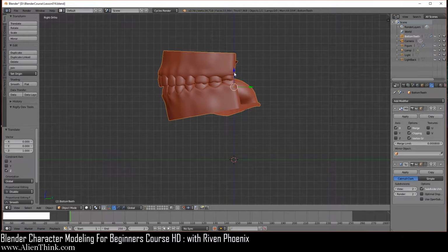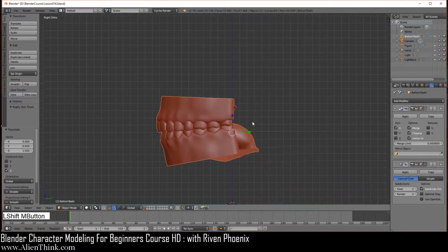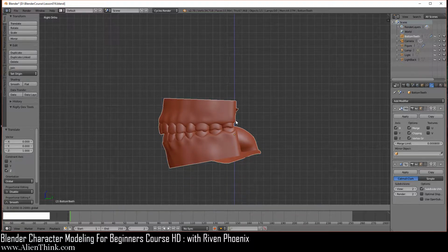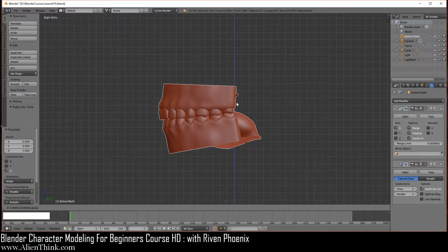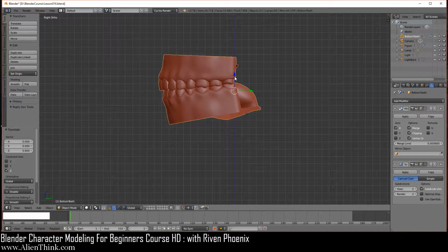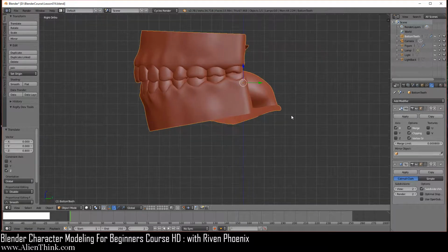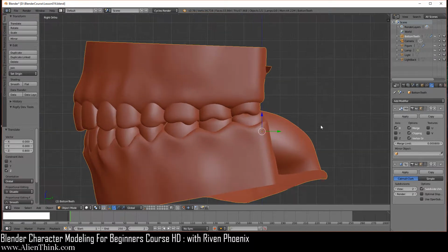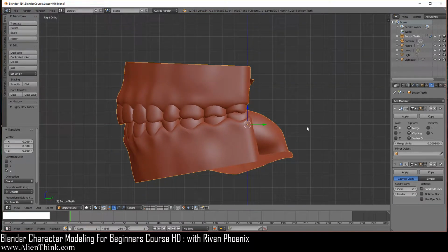I'm going to let the left mouse button go. Then shift middle mouse button to pan it down again. Now we're going to move it up 8 nudges. So click on the blue arrow, take it up 1, 2, 3, 4, 5, 6, 7, and then 8. Okay, now just zoom in like this, shift middle mouse button over here. Now what you want to make sure, see the smaller grid unit? So here I'm just going to zoom it out so I don't see that.